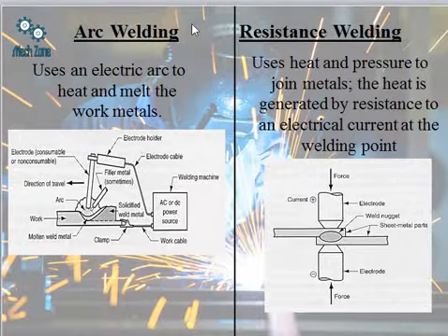But it's a very obvious fact that DC is more dangerous as compared to AC, because the constant magnitude and the direction of DC never changes, whereas in AC it may reduce to zero at a certain point because of its sinusoidal nature. And there is a phenomenon called arc blow, which is limited to DC arc welding, and we'll be studying about the arc blow in the upcoming slides.